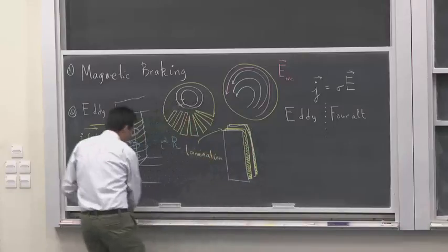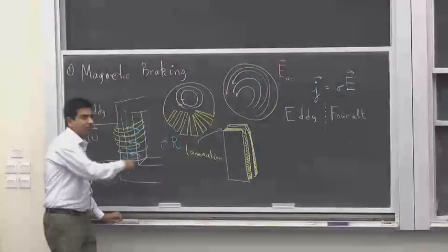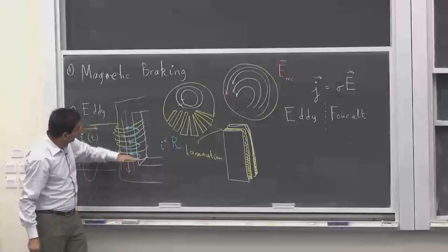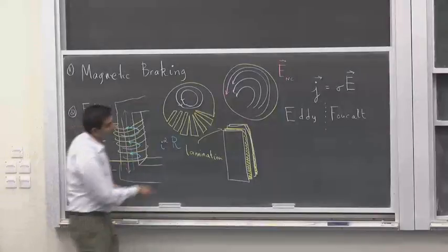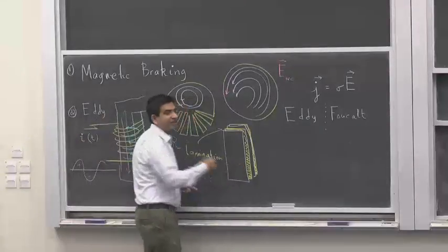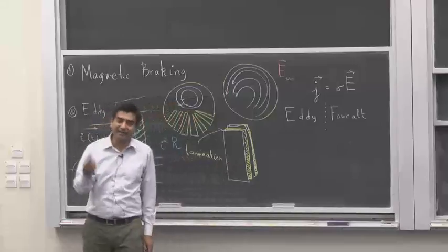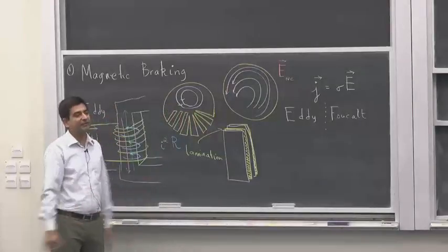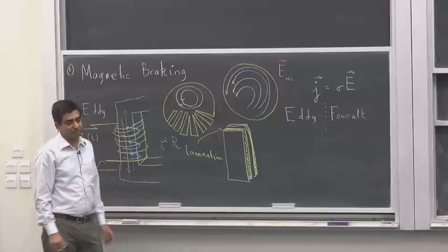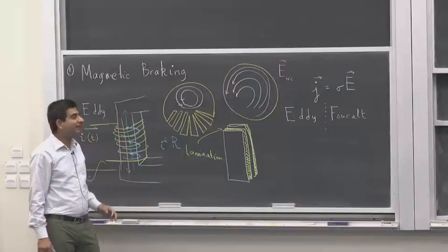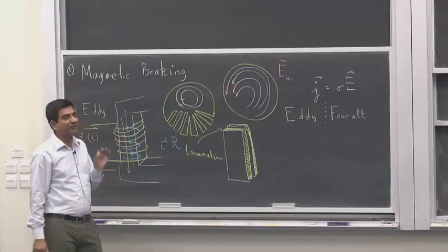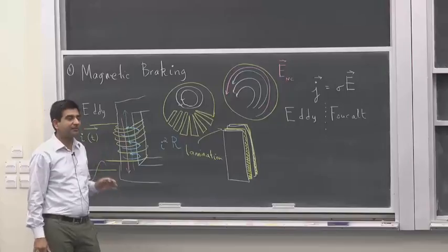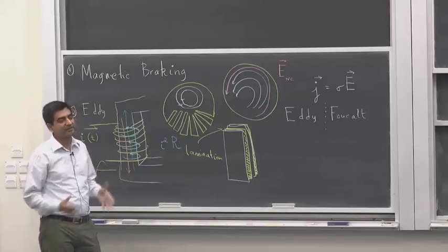So now eddy currents that are produced in a plane which is horizontal have to pass through this insulating material. So the eddy currents will be reduced. And when the eddy currents are reduced, I squared R is going to be reduced. So the heating of the transformer can be kept under control. So eddy currents are really important when you're designing magnetic systems or systems that use electricity and magnetism together.